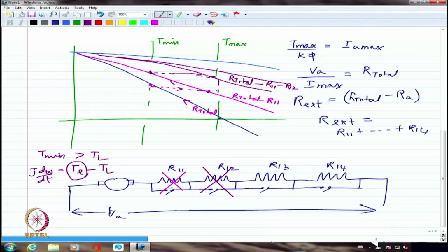So the manufacturer's data will tell me the average current or the steady state current can be 10 amperes. But for a short while, you can probably pass 20 ampere. That short while they will decide, they will probably tell you 20 millisecond, 40 millisecond, 1 second, whatever. So I should know the inertia of my load as well completely. Only then I can say how long it will take for the back EMF to build up. Right? Got it?